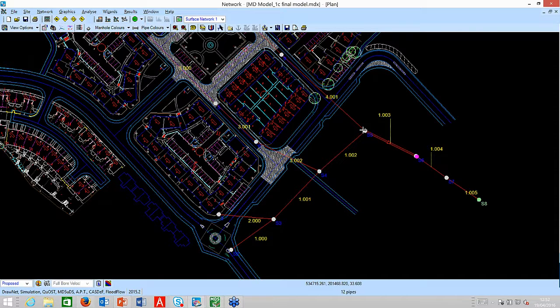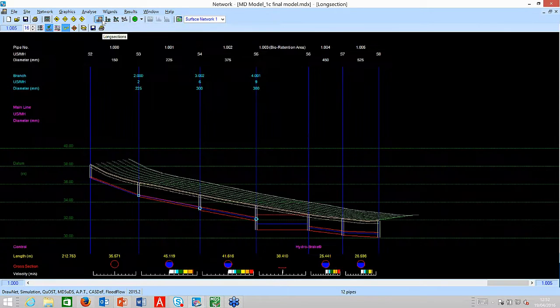The other thing that I did, I looked at the invert level because it would have taken up the slope of the pipe. So if I take a look at this in the long section view, these are all the upstream pipes and manholes feeding down into this, not a pipe anymore, but a bioretention area, which I've laid flat with that pipe and under drain pipe effectively connecting back into the downstream pipe network.